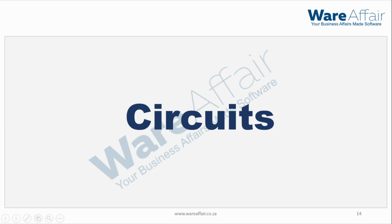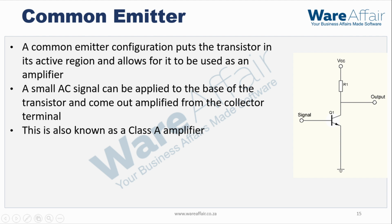Let's look at transistor circuits. First is the common emitter. A common emitter configuration puts the transistor in its active region and allows for it to be used as an amplifier. A small AC signal can be applied to the base of the transistor and it comes out amplified from the collector terminal. This is also known as a Class A amplifier.